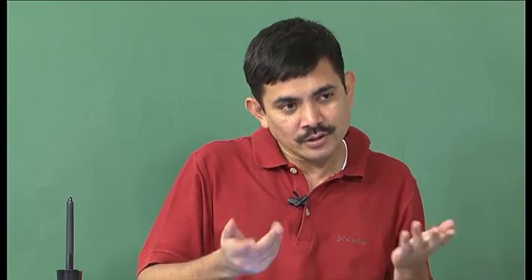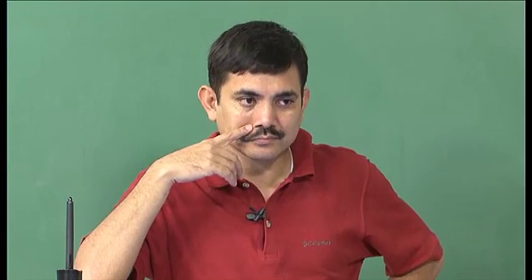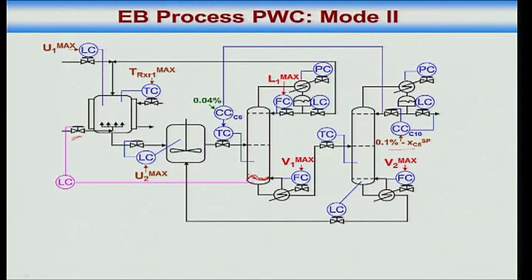That means the level control is fragile. ये बात हजम हुई? It's very fragile because I make a change in ethylene, and by the time the effect comes to the bottom level, it may have run dry or it may have overflown, and that is what actually happens. Okay, so it is fragile, and it's fragile because of the large residence time in the reactors.